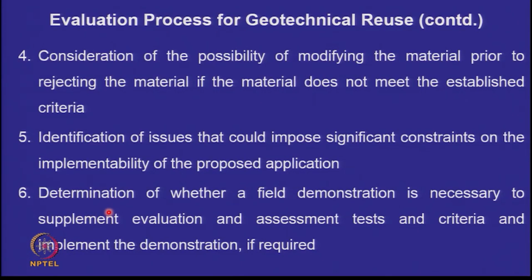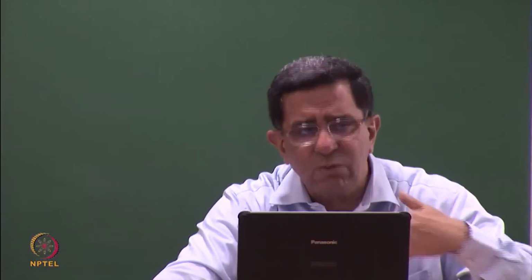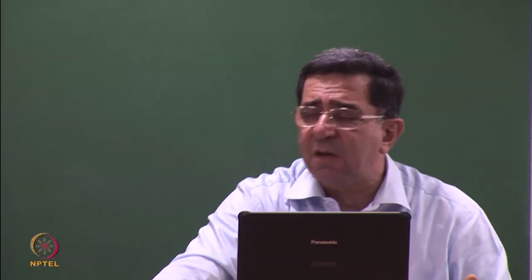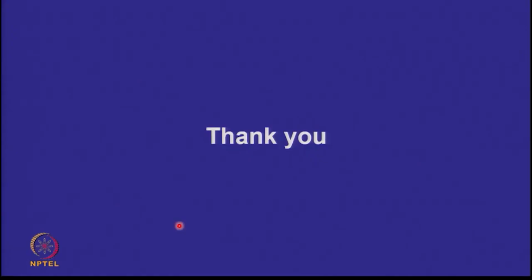And also, it is nice, if you are dealing with something new, to have a demonstration project. Theoretically, everything may seem fine, but if you are making an embankment of a new material, defer it, do a 6 months demonstration project, make the embankment, make it go through the summer and the monsoons, and then if it looks fine, adopt it on a full scale basis. So, with this spectrum, you can